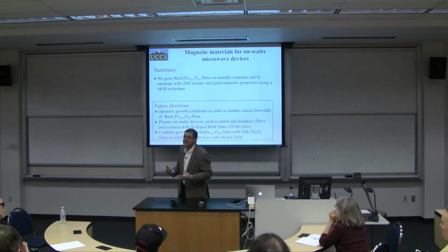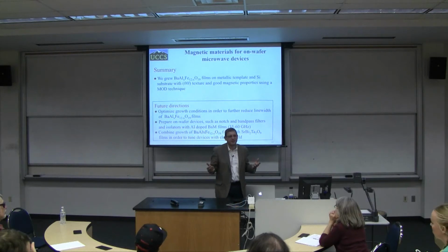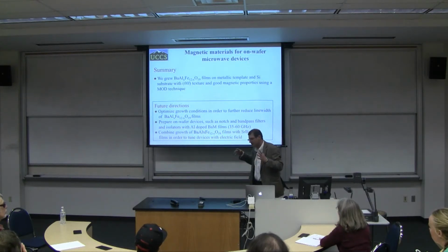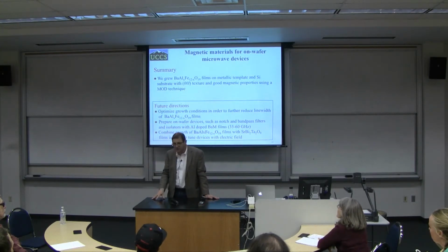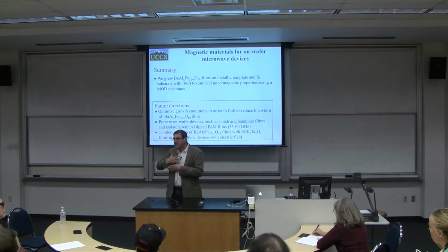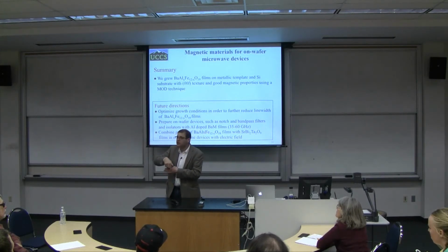To give you a trivial example, think about a material like PZT. It's not this one, but PZT is a ferroelectric which has a big piezo effect. If you apply the voltage, you are physically changing the size of this film. Therefore, this film on the top is going to act on this one by pushing it down.